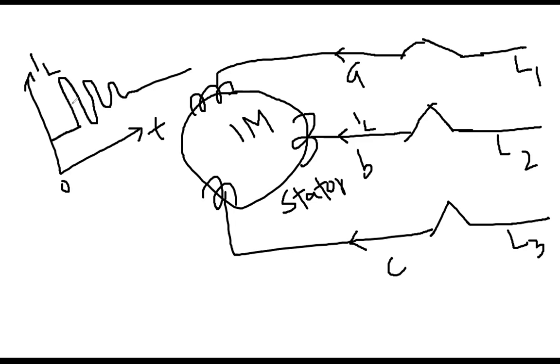That is detrimental for the circuit, because a very high value of current will flow into the stator coils. These coils might be overrated and might be immediately burnt. So that's why it is not advisable to close the circuit in that manner. So then what do you have to do?